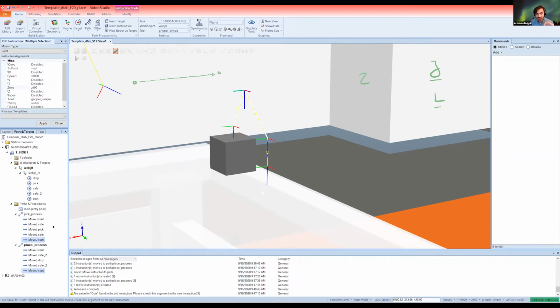So when you're doing a Move L, the robot tries to make sure that the TCP and the tool are exactly moving linearly between two targets. It is sometimes super helpful when you are doing something accurate. But if you want to make a big motion from one part of the space to another, or if you want to quickly move between two points without being concerned about the type of motion,